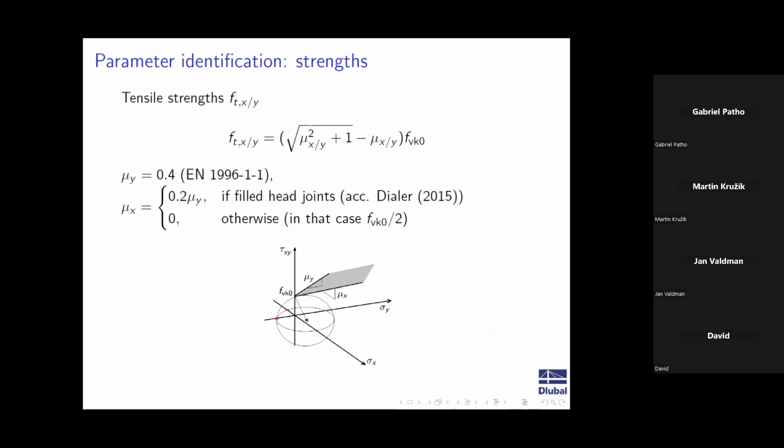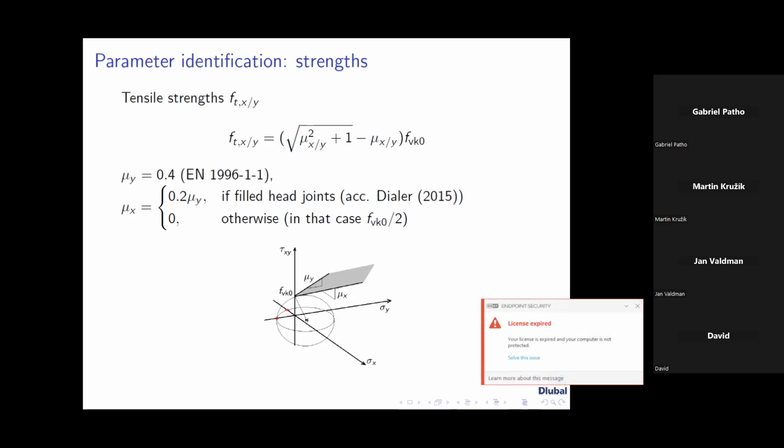So what my colleague did is to assume I have 0 Poisson ratio. So I have my confining stress in the respective planes, in the normal stress versus the shear. He extrapolated it into a linear plane, and he was asking where is the center of a sphere that has this plane as the tangent to that point.